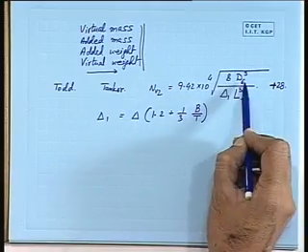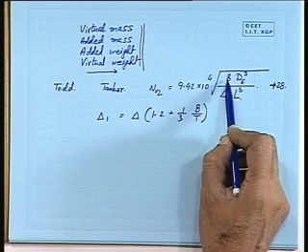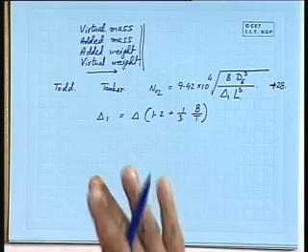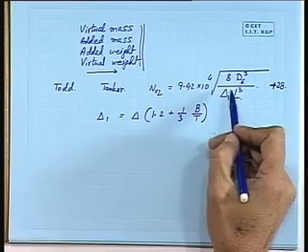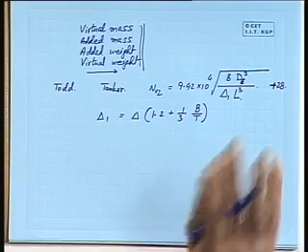Now, you see here, putting it in this condition, B D E cube. The other day I told you that while taking the second moment of area, for a rectangular section it is 1 by 12 B D cube. So he has tried to follow that, and E stands here for D equivalent.